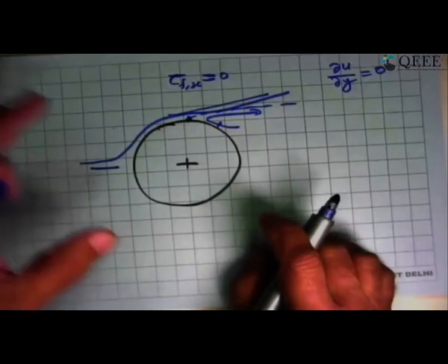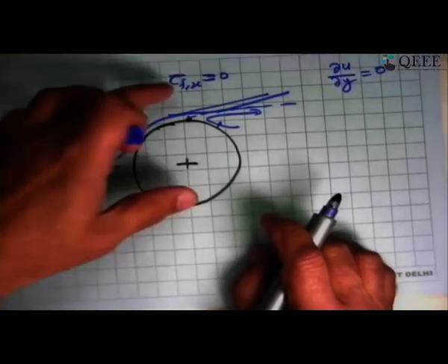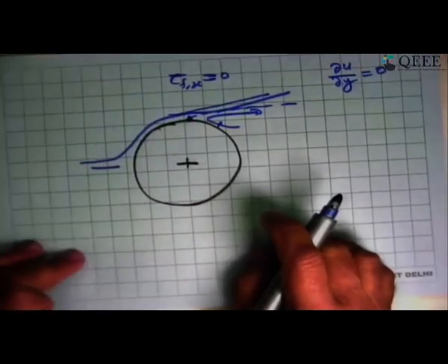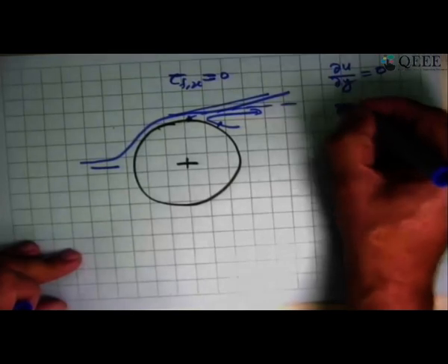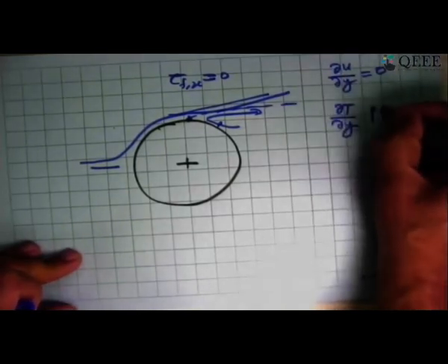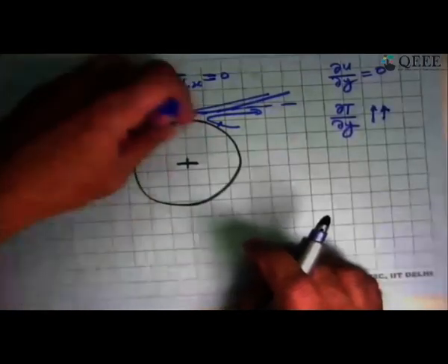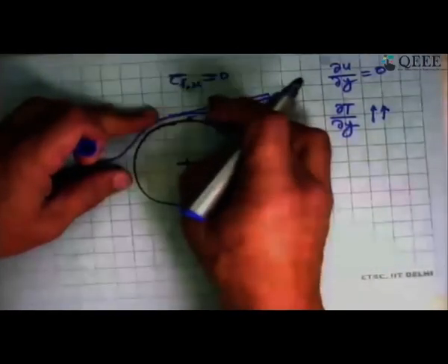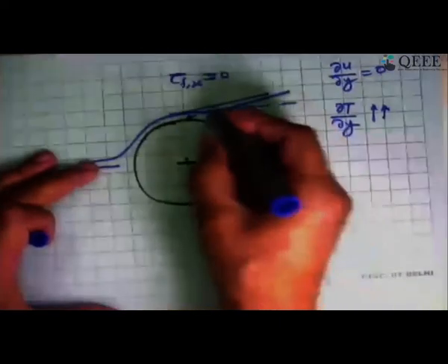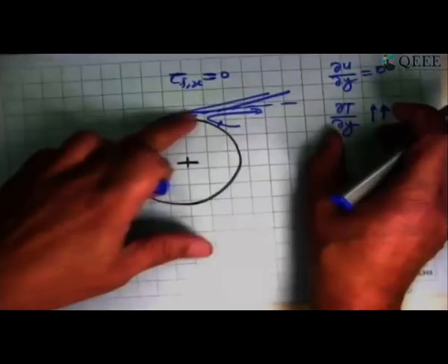So in the fluid flow case, this is what is happening, but in the thermal case, this is not going to be 0. It is going to remain finite. So you would still have some dT/dy, which in this case is going to be very large, because the fluid is not taking away its energy, it is only taking it just by conduction. So it will at the same point cause a very low heat transfer coefficient at that point.